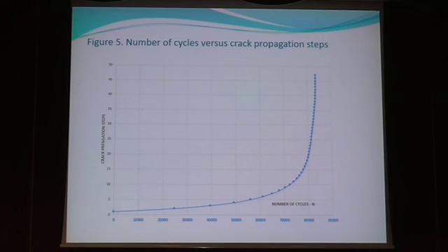So the curve that I mentioned is given here, crack propagation steps and number of cycles. So at about 70,000, you may notice a relatively significant increase in crack growth rate. So from an engineering point, it's a bit arbitrary, but from the engineering point, you may think of 70,000 cycles as being critical for this specific welded joint or specific structure.